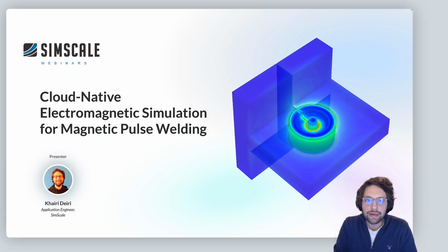Today, we are analyzing the electromagnetic efficiency of a magnetic pulse welding system, specifically focusing on the sensitivity of magnetic pressure to changes in the transient electric load. Using SimScale's transient electromagnetic solver, we will sweep through the electrical conductivity of the flyer tube to simulate different aluminum grades or thermal states, which would represent a common scenario of working with different suppliers where variety can happen quite often, right?